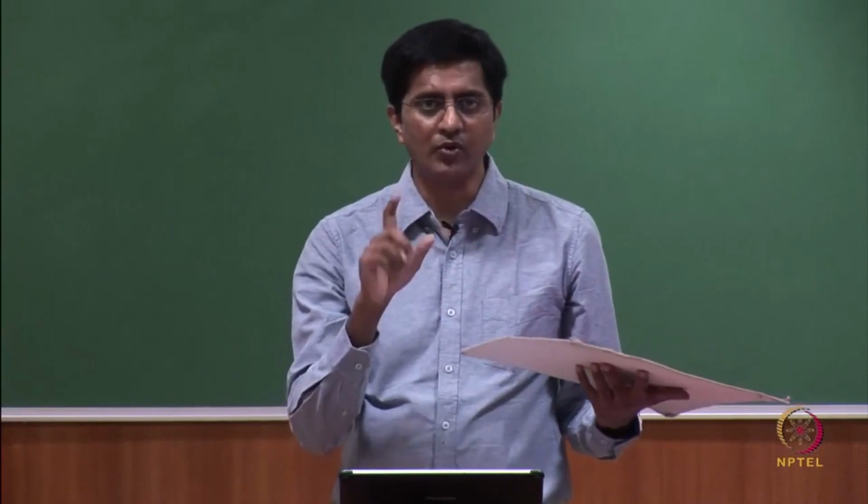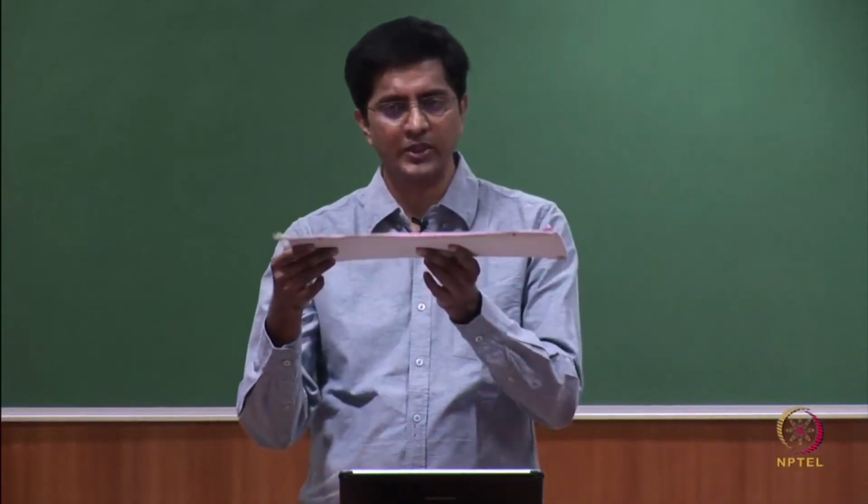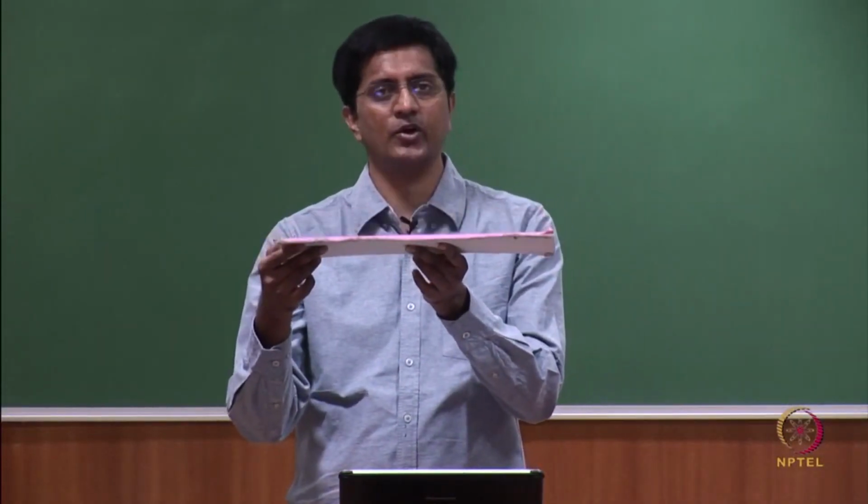To capture the top view, what we will do is we will use information from the previous views as well as the current view. So, we will use the front view. So, first let us draw the projections from the front view, and we will also get the projections from the top view from the previous step. So, we have broken this problem into a two-step problem. In the first step, the plane is simply oriented.